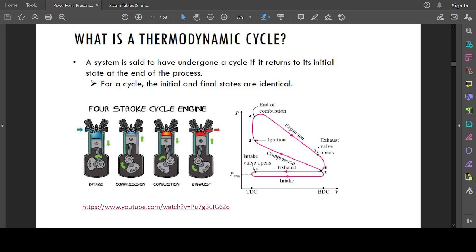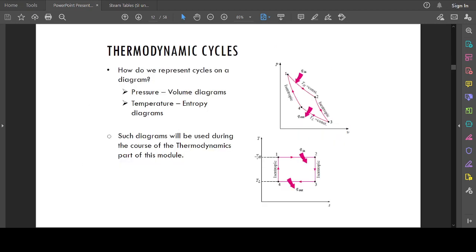That explosion causes a very quick rise in pressure, which is the expansion due to the combustion, the mini explosion in this case. And when that happens, the crankshaft returns as the pressure dissipates, and the exit valve opens, and the exhaust gases are pushed away, and the pressure returns back to its original, and the system continues because it's a cycle. It continues in that motion.